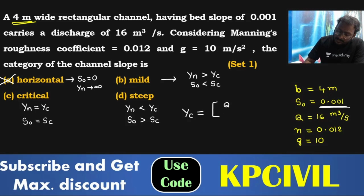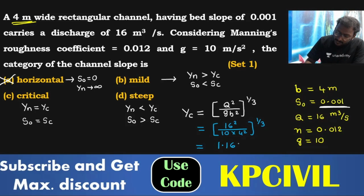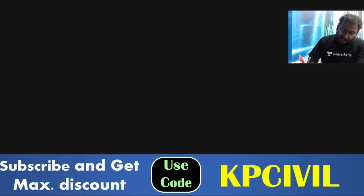Yc is easy. Q square by G B square, whole power 1 by 3, that is Yc. Q is 16, square, G is 10, B is 4, square, whole power 1 by 3. Calculate it. So I am deriving the relation between normal depth and critical depth now. Substituting the values, we get critical depth as 1.16 meter. Yc value is 1.16 meter. Then you need normal depth.